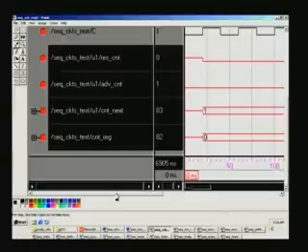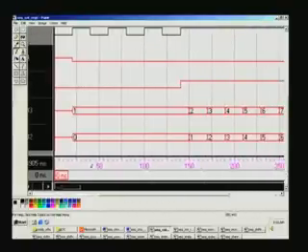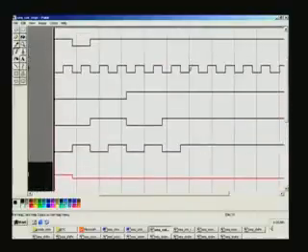The last one is counter reg, and you can see the time axis clearly here, 50 nanosecond and so on. So, it is around I think 20 nanosecond it goes to 0, and that is what we had put in the test bench, and here it starts incrementing only at this edge. This is the edge that is at 150 nanosecond, and corresponding to that the clock has become active there. That is, a rising edge of the clock is noticed, and here ABC conditions are 1 here, 1 here, 1. This is ABC, and reset is no longer active. It is active during the low phase here.